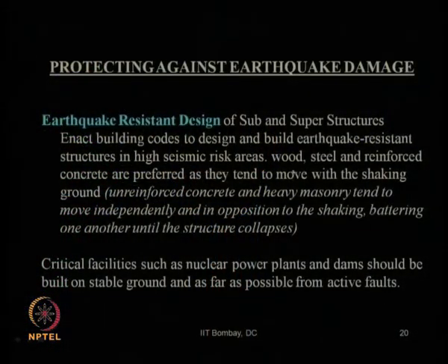So, materials like wood, steel, reinforced concrete are preferred as they tend to move with the shaking ground, whereas unreinforced concrete and heavy masonry tend to move independently and in opposition to the shaking, battering one another until the structure collapses. In simple words, in a high seismic risk area, it is better to avoid unreinforced concrete and masonry buildings.